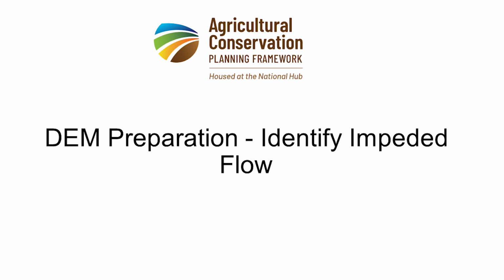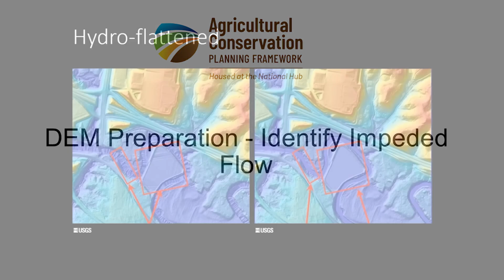In this video, we're going to discuss the Identify Impeded Flow Tool. But first, we will go over some considerations for using a LiDAR-derived DEM. We'll be introducing concepts such as hydroconditioning of DEMs and some pre-processing that you should do on your DEM before conducting any sort of flow modeling across the landscape.